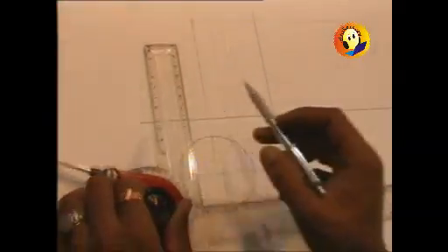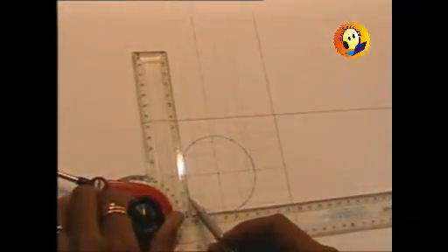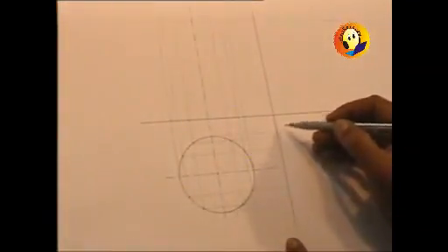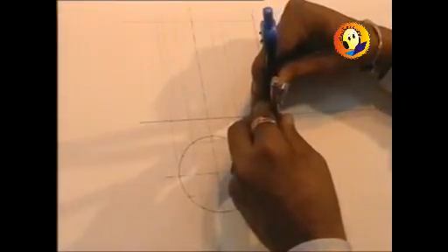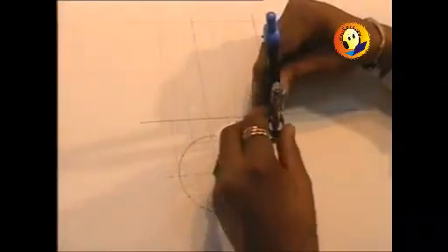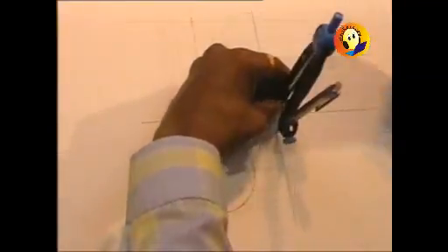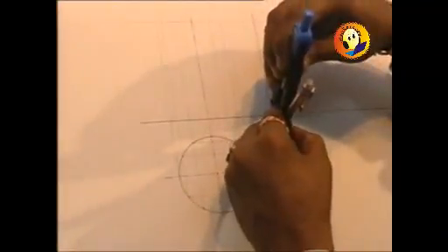So we are required to draw 12 generators in the front view, and even in the side view those 12 generators should be drawn. I had taken those 12 generators till the vertical line, and then using the intersection point of that vertical line with XY as the center, we will be rotating each of these lines up to the XY line itself. All the lines are to be rotated.